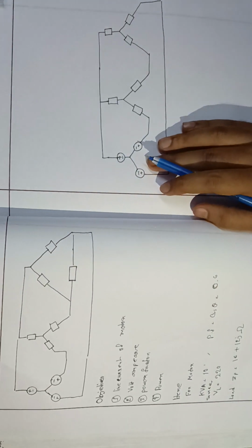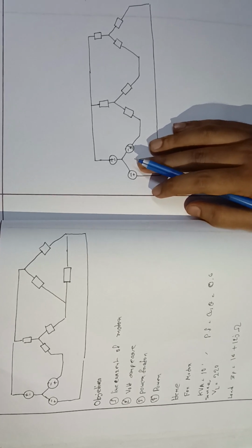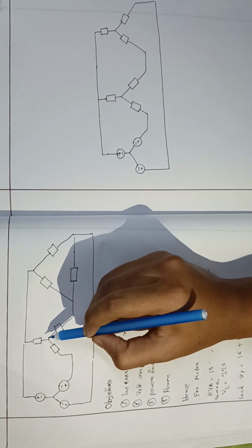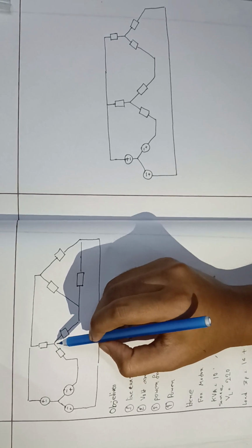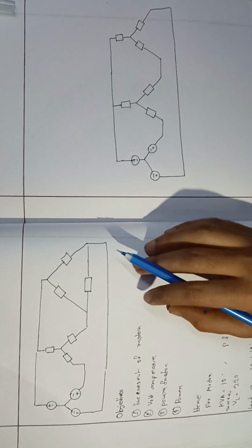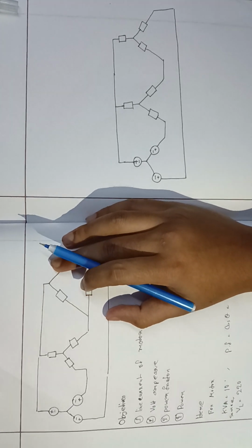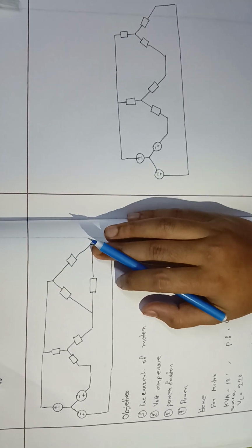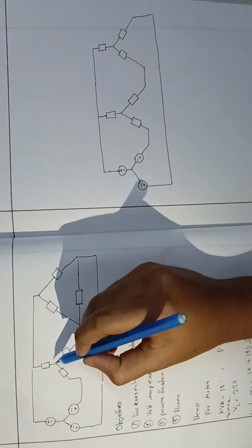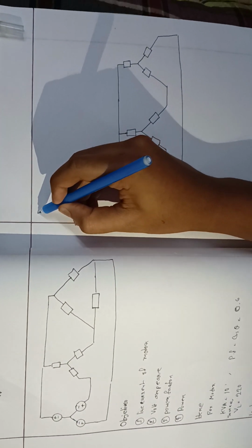Today I will show you how to measure power, volt ampere, line current and power factor of a combination which has a motor that operates at 10 kVA at 0.8 power factor lagging from a source of 220 volts. It is in parallel with a load that contains an impedance of 16 ohms plus 12j capacitive reactance in series with each phase. So assume the motor is in YY connection, and in a YY connection we know that IL is equal to IP.